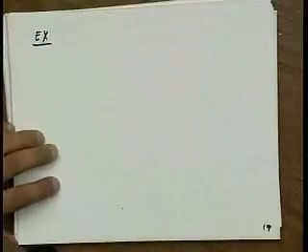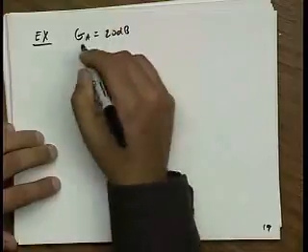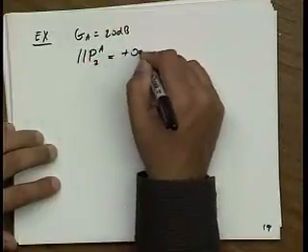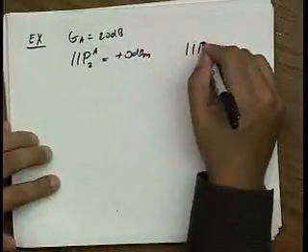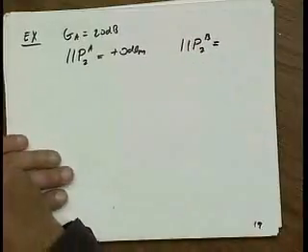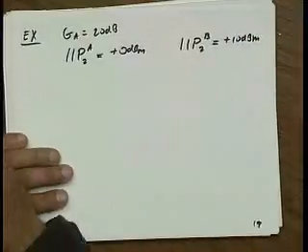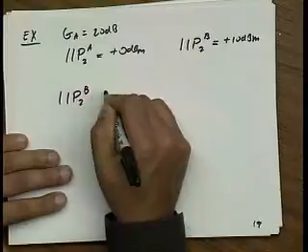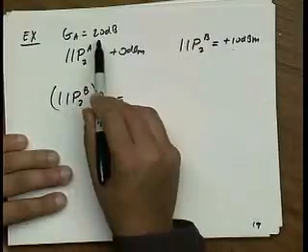Let's say that I have an amplifier with a gain of 20 dB and an input IP2 of plus 0 dBm. And now let's say I pick a second amplifier and it has an input IP2 of only plus 10 dBm. Now that sounds pretty good, but if I input refer this, I have to take this gain into account.